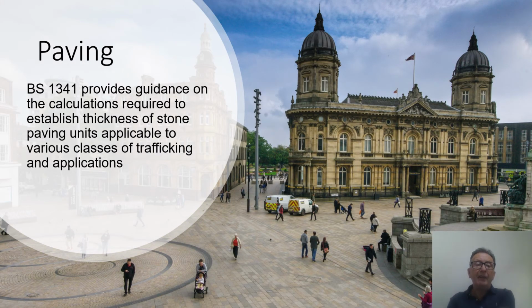For external paving, the most relevant standard would probably be BS 1341. This provides guidance also on how to calculate the required thickness for a stone paving unit, and it gives advice and guidance with regards to different classes of trafficking in different applications of use.